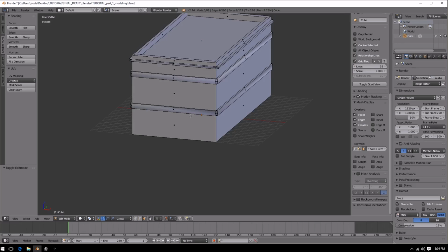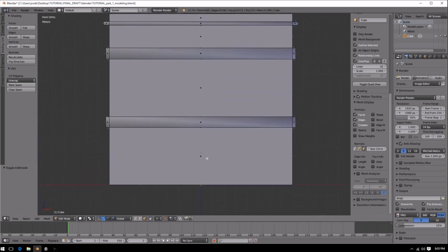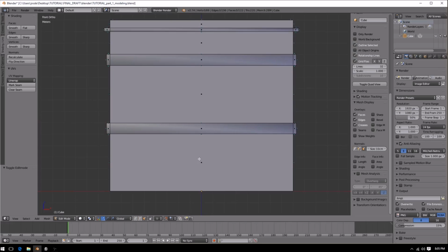Anyway, let's go ahead and add a door, and what I want to do is go to the front of the model. So if you recall, let's hit the 1 key on the number pad. Zoom in a little bit. I'm going to pan this up. I'm going to use the 3D cursor to snap a new shape right onto this face that I'm circling here.